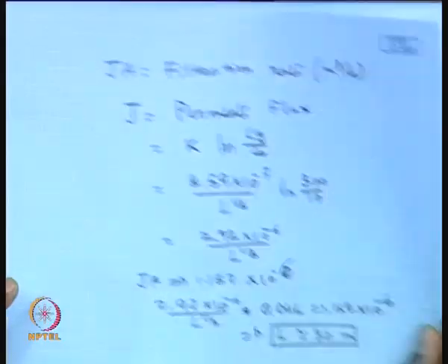Okay. So, you require about 30 meter of membrane module to get this much of filtration area if you put membrane only at the bottom of the channel. Now, it is difficult to get a 30 meter, that means around 90 feet of the module. So, you can even break down this module into 3 small modules and keep them, let us say 10 meter each, or 4 or 5 of them, and put them in parallel. Okay. So, that will provide that much of membrane area.